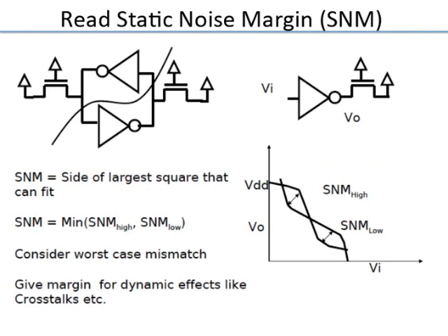If the noise margin minus 5 sigma is not a positive number, what it means is some small fraction of the cells could have 0 or less noise margin. That means they will not work. So like that, you have to basically do a statistical analysis for the cell. For every design, you say I'm going to use my V cell to be 1 volt, V word line to be 0.7 volts. Then you have to do this and see is that good enough. You have enough percentage of cells which will have positive noise margin.